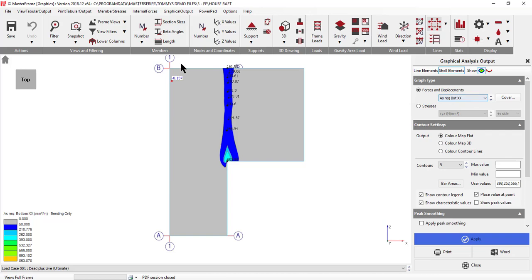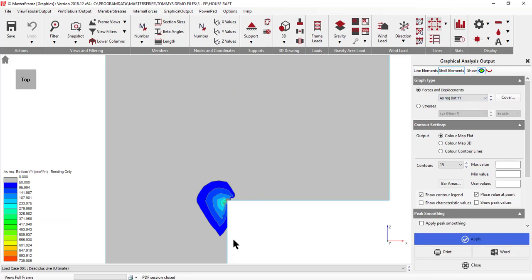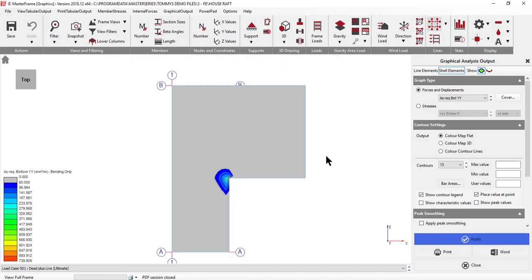The Y-axis, there is a little bit, and it's all very concentrated over these line loads on this surface. So you can see here you're up to 300 just in this one corner. So in my case, I would say, well, really 8s at 200 will be satisfactory. I might as well use 252 mesh. However, in this zone we would just put some additional reinforcement in to make sure that there's no cracking around that corner, and then we would move to the bottom in the other direction, and we'll see that again there's nothing other than this one area.